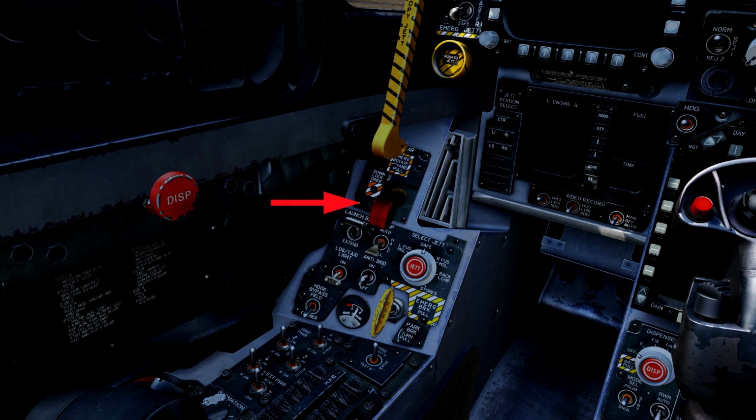And here at the top of the left vertical panel you have the landing gear handle, which controls the tricycle landing gear and is based on weight on wheels and the launch bar condition. And right next to it is the down lock override button, and by pressing and holding this button it retracts the mechanical stops from the landing gear handle, and this allows it to move down to up in case of a failure. And the last element of the left vertical panel is the canopy jettison handle, which is the big black and yellow striped handle here.